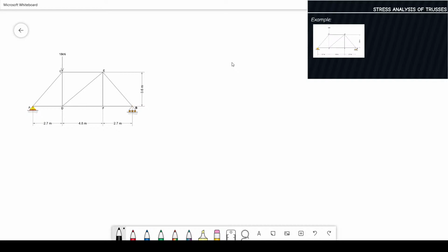So in analysis of trusses, what I do first is to find the angle. By the way, in analysis of joints and method of joints, we are to analyze from our left side to the center, then from the right back to the center, so that at the end of the analysis, you can cross-check using these members. Okay?